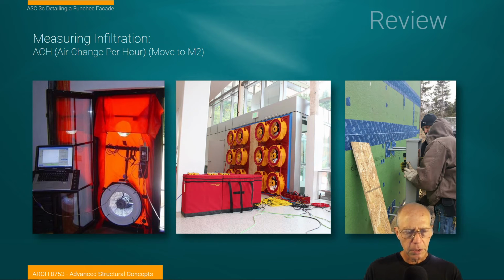So they have these fans that they apply to the doors. They suck the air out of the building, and they do that in a continuous fashion. And then as air starts to leak in, you have a pressure differential between the inside and the outside. So these systems allow somebody to quickly calculate, by exhausting this air through the doors, how much is entering through other areas, and that can determine the air tightness of the building and then the air changes per hour. And so that is just part of what's happening in the advancement of analysis of performance.